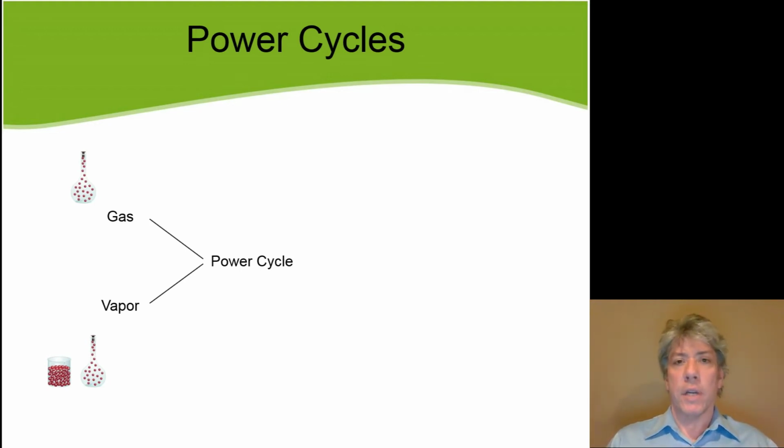That way it has a very high specific volume, a low density, and as it goes through the turbine it can do a lot of work because of the principles of reversible work and how a large specific volume will typically yield a large amount of work per unit mass.